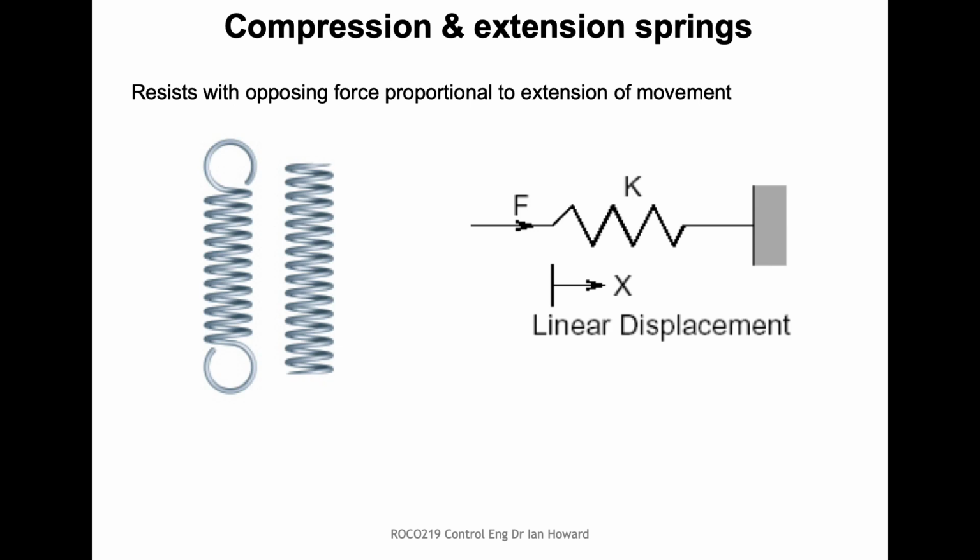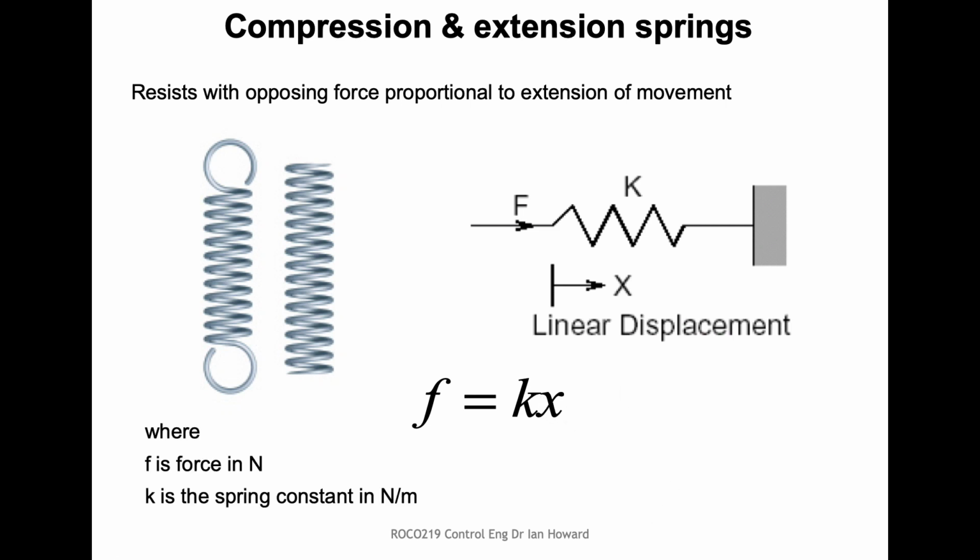But basically, we pull this spring at resting length. There is no force needed, and we define the extension from how far we are from the resting length. If we then pull this thing, what we're going to get is a displacement from the resting length. As long as we don't pull it too far, it'll be a linear displacement. And for this linear range, we can say that the force we apply is equal to the spring constant times the extension we're going to get. So F = kx. And we're going to use force always in newtons, and k is going to be newtons per metre.